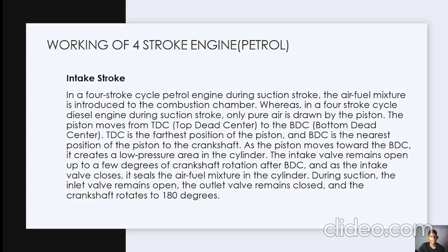First stroke is intake stroke. In a four-stroke cycle petrol engine during suction stroke, the air fuel mixture is introduced to the combustion chamber, whereas in a four-stroke cycle diesel engine during suction stroke, only pure air is drawn by the piston. The piston moves from top dead center to bottom dead center. Top dead center is the topmost position of the piston.